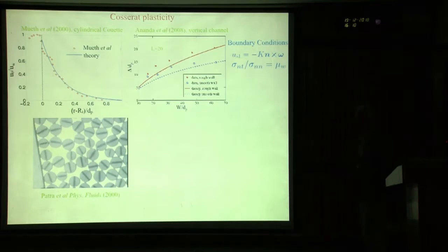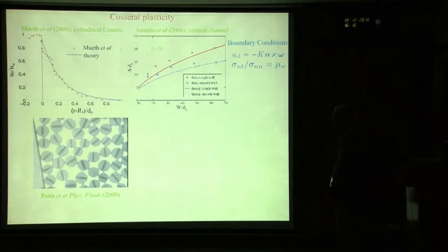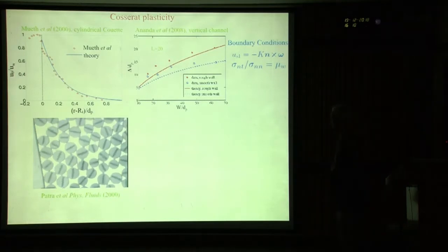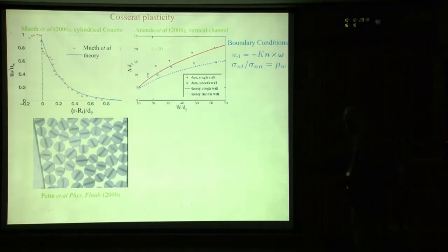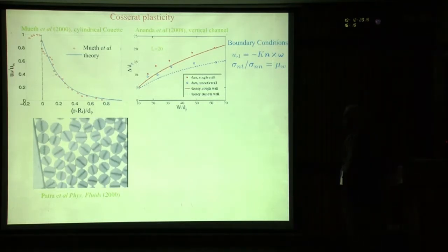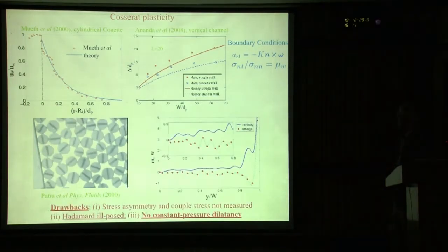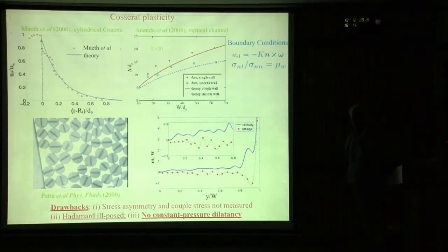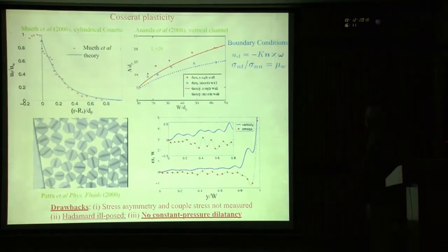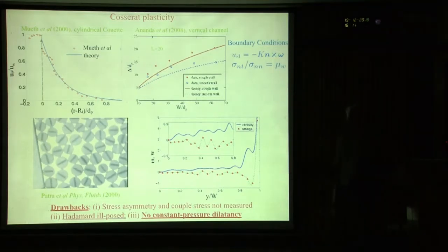Now, there's a little bit more evidence for this Cosserat plasticity, although in the end I'm going to abandon this. Here we did experiments of aluminum discs going through a very narrow, or rather small angle, hopper, and measured the particle spin, and from the mean motion we could get the vorticity. For a hopper, they are of different signs. They're not just slightly different. The vorticity is positive and the mean particle spin is negative.